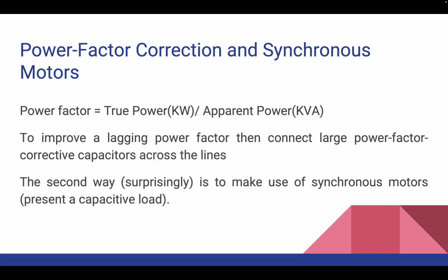A purely reactive load with a 90-degree phase shift between the voltage and the current results in a power factor of 0, indicating that no real power, or true power, is being consumed by the load.